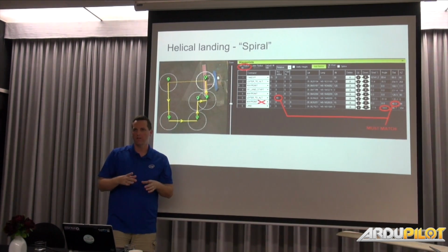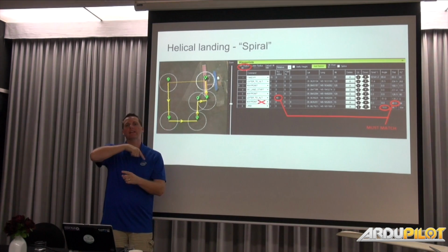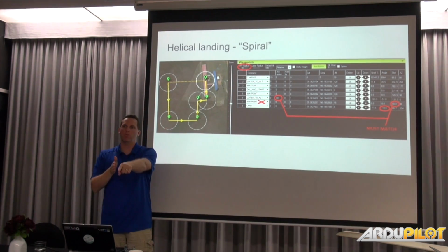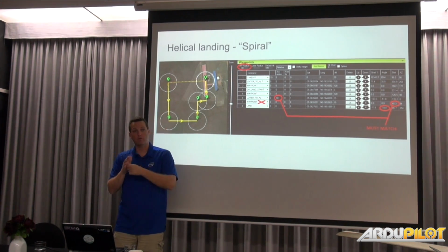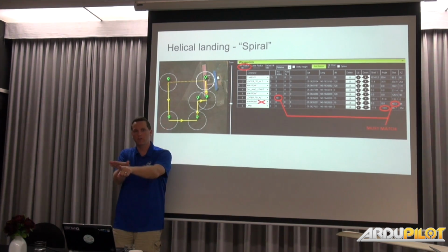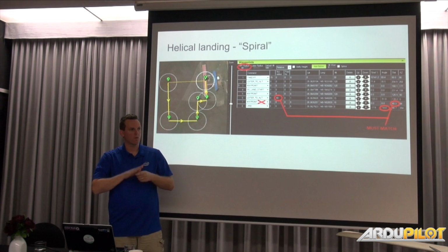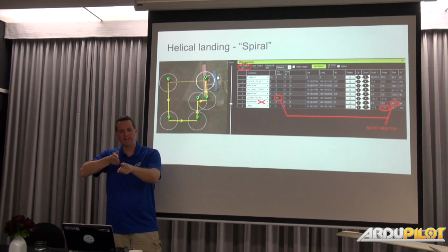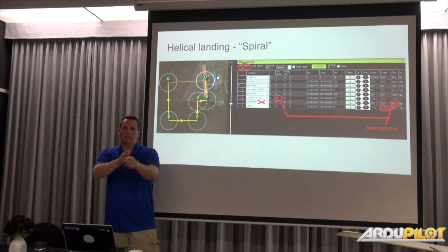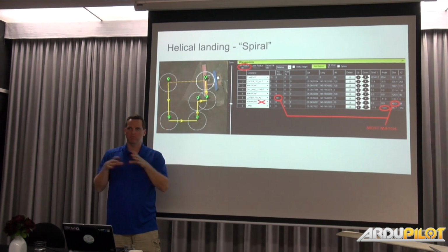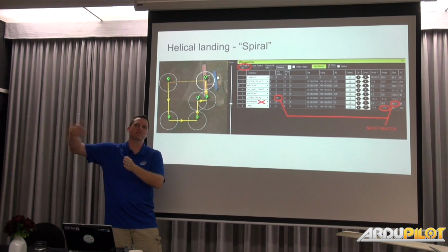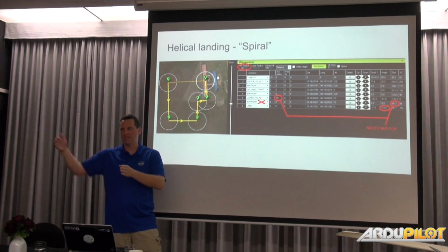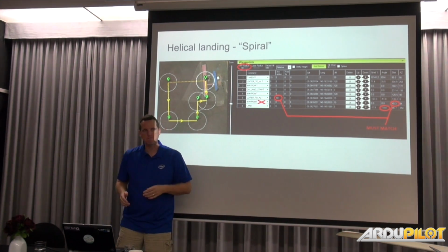Also on the tangent exits, they don't exit until you are lined up to the next point. So it grabs the heading and says your heading must actually be aligned. Your ground heading, not your actual heading, because you're yawing in the wind or crabbing. So when you exit, you should just be lined up, and you should just go straight into the next point. So you don't want your radius to be different. If you have some huge radius and then your bottom is here, then you're actually still going to be tangent exit and then still swerve in.